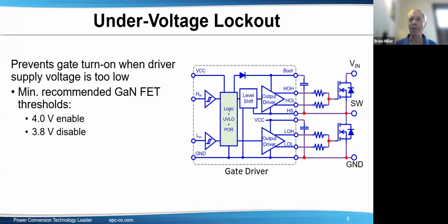One thing to be careful of is some controllers may have their own thresholds. And I've seen cases where you can adjust the gate drivers for, say, 5 volts, but the undervoltage lockout could be even above 5 volts, or 4.9 or 5.2 or so, worst case. And that's clearly bad. You would be right on the edge of turning off the gate drivers. So something like this gives plenty of margin, yet ensures that the gate voltage is high enough.